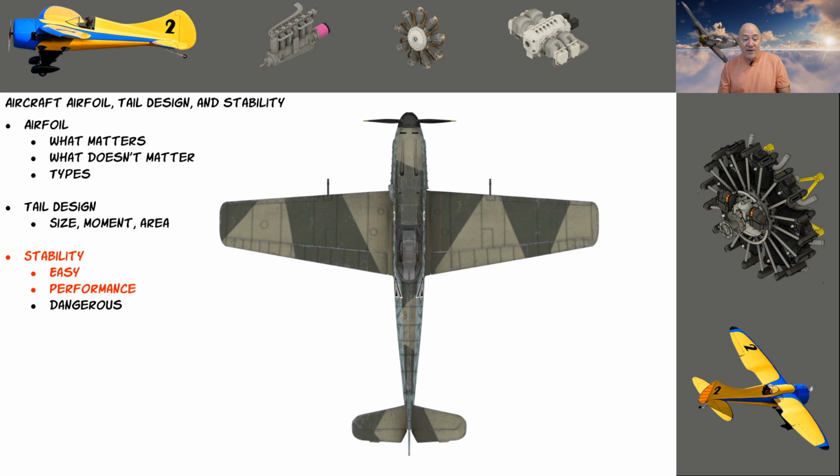Now, if you scratch build an airplane and you look at the size of the horizontal stabilizer, let's say you want a small horizontal stabilizer. Make that tail a little bit longer. When I look at the 109 here, I always am amazed. Same thing with the Spitfire, how small the horizontal stabilizers were. I like to be in that 25 to 30%. This is less than 25%. I think this is something like 19%. But it had a long tail, so it was stable.